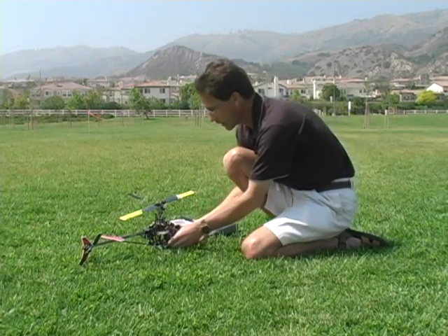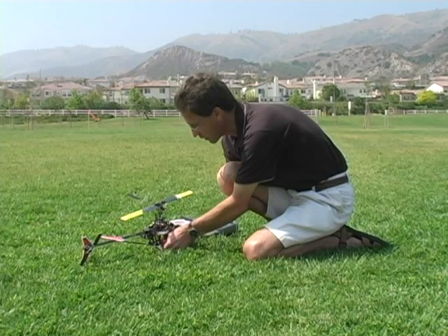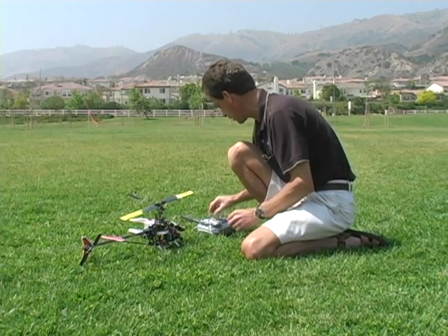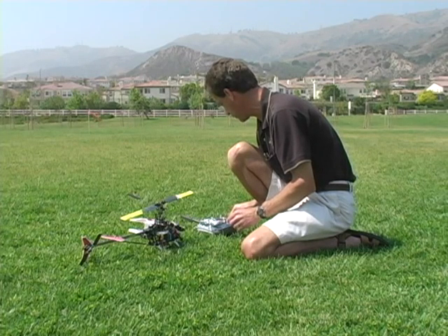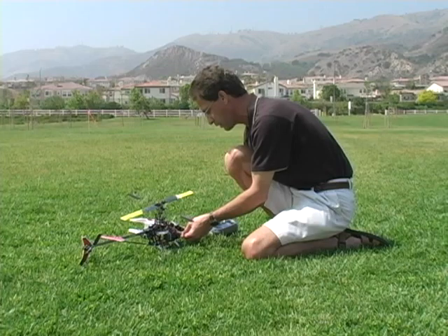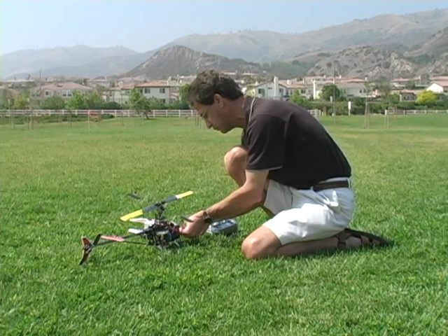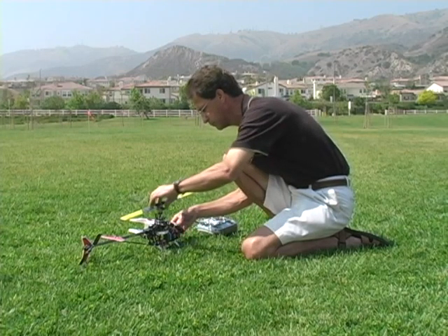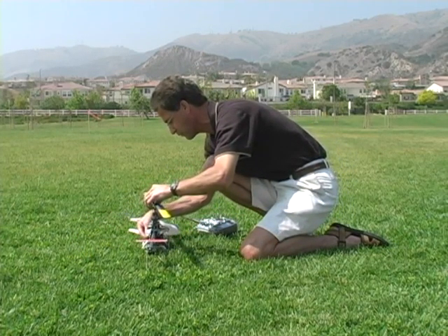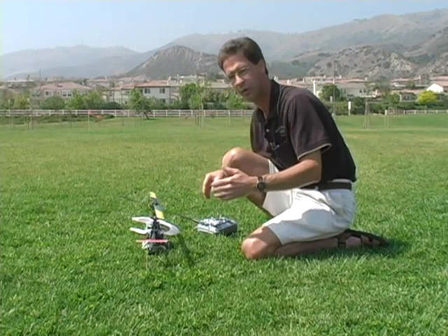I do need to disconnect the motor before we do this because the main way that I'm going to see if the radio is working is by moving collective pitch. So, okay, we are T-Rex DVD, that's good. Everything's low, let's power up. And I'm just going to face the helicopter so it points toward the radio.